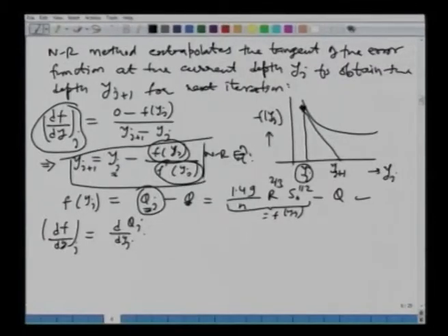Let me go back, this is actually your velocity. So, I need to multiply this by area somewhere. So, in this equation your R is a function of y, and also the area is some function of y j. So, now you have a product of two functions which depend upon depth of flow. So, what will be dQ over dy?